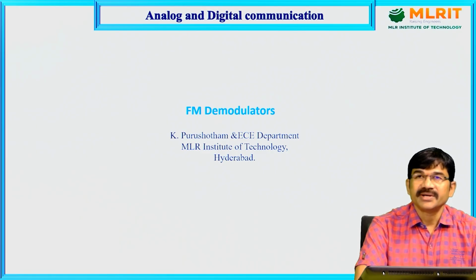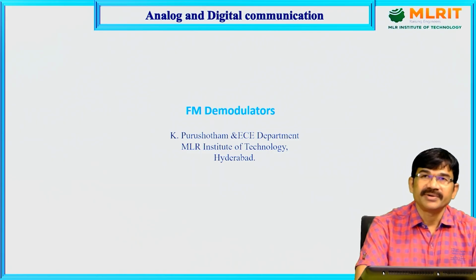Wideband FM we again classify into two types. The first one is the direct method of generating wideband FM by using the voltage controlled oscillator. The second one is the indirect method of generating wideband FM. Another name for the indirect method is the Armstrong method. By using the Armstrong method, first we generate the narrowband FM, then we multiply the frequency by using the frequency multiplier. Then we get the wideband FM where the beta value is greater than 1.